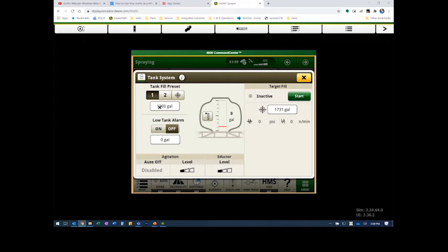If I have a 1,200 gallon sprayer in this case, and I go to do a full refill, I can have this set up to have 1,200 gallons, or a lot of guys do like 1,230 or 1,250, what the machine actually holds. When I do a refill, I can hit the button there. It'll give me the full refill and go from there. Or if I batch it and I only have a half load, I can select my preset. I can also adjust that number by clicking there, and then press my fill button, and it'll adjust based on what I tell it.